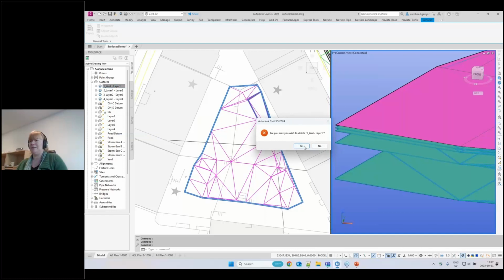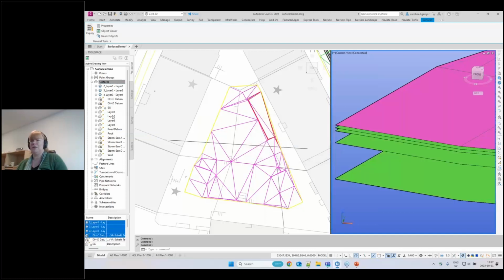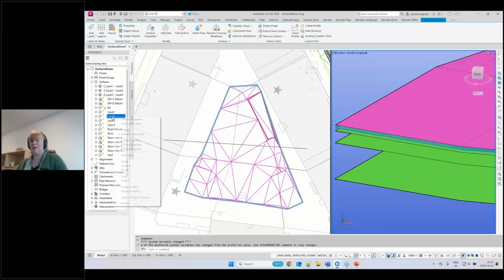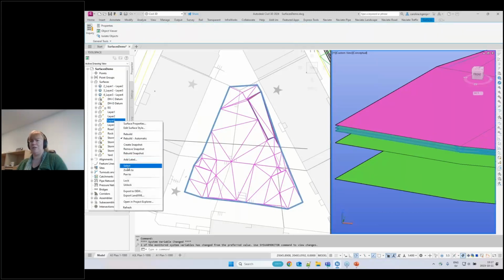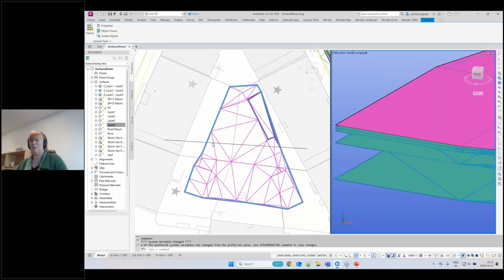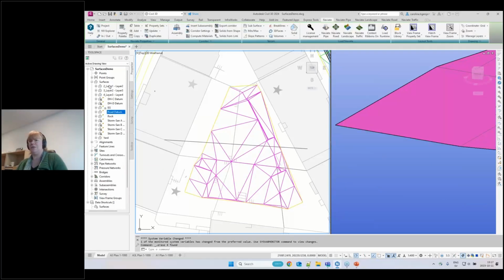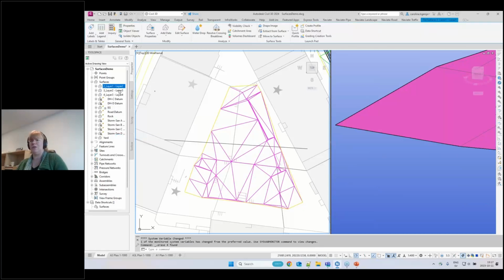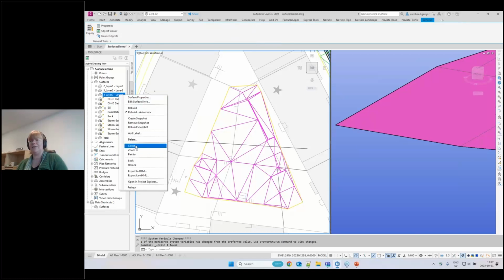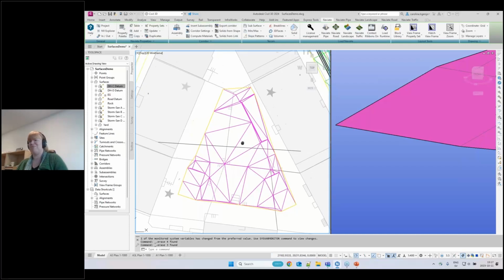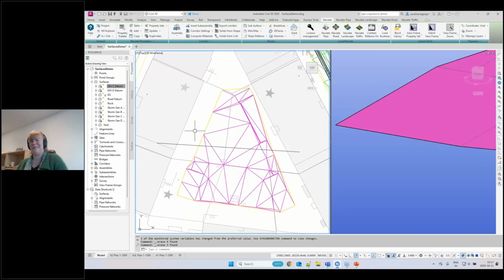So if I want to delete these surfaces, I need to select them. So I really should have selected it. That was my intention. Select them all by right click and then use delete to remove them. Now, selecting the objects via tool space is also a good idea because then you're sure that you're not accidentally selecting something that was important in your drawing. So also a handy tip to select stuff from your tool space instead.